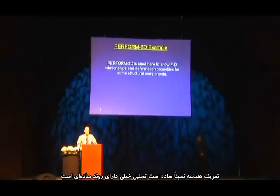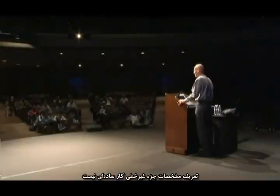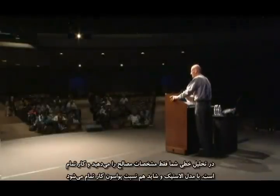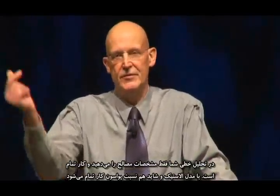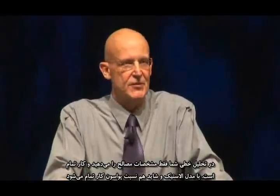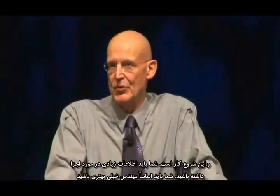When you're building a model, most of your time actually is going to be spent in that component properties portion of the input. Defining the geometry is relatively simple. Defining the nonlinear component properties is far from simple. In a linear analysis, it's a simple process. You just give material properties, you're done. Elastic modulus, maybe a Poisson's ratio, that's it, you're done. Nonlinear, no way, you've just begun. That's the beginning.